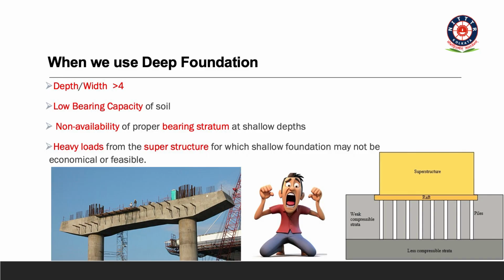So when will you use the deep foundation? We should understand these four criteria. When depth by width is greater than 4, we call it a deep foundation. Also where the soil has low bearing capacity, we go for the deep foundation, and also where there is non availability of proper bearing strata at shallow depth.